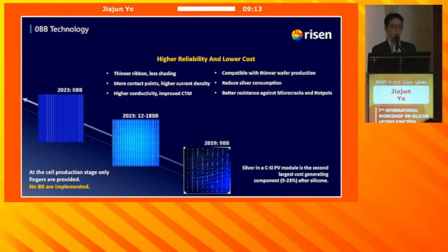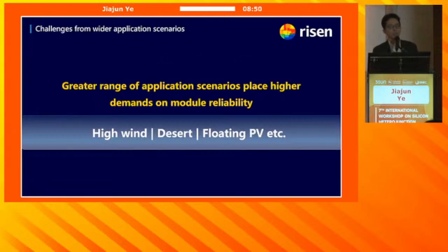This way, we can reduce the shading that could cause power loss and hot spots. The thermal stress on the surface is also more balanced compared to before, because we don't have welding points or pad points on the surface to attach the ribbons for fixation. By introducing this, we are already reaching quite reliable products in terms of microcracks.